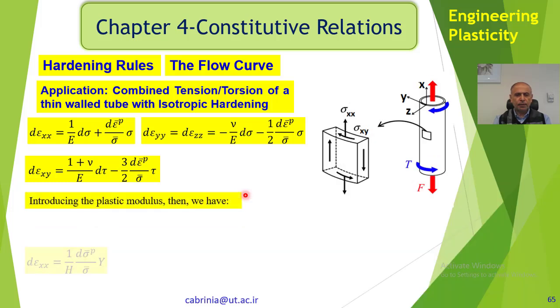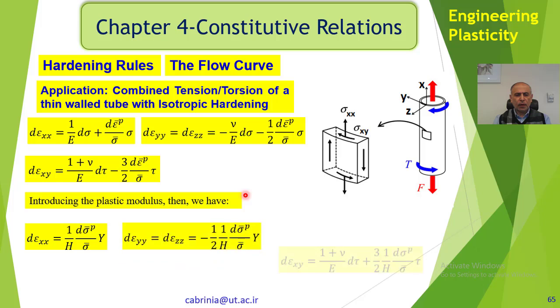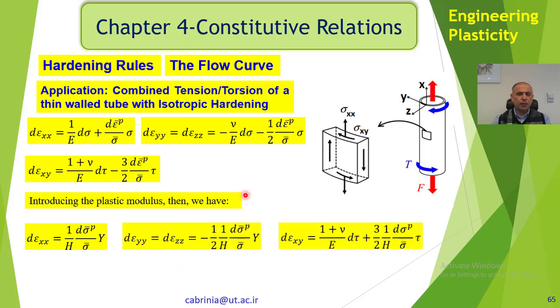And introducing the plastic modulus. In fact, the plastic modulus, you remember, was the gradient of the curve. That H was d sigma bar to d epsilon bar p.